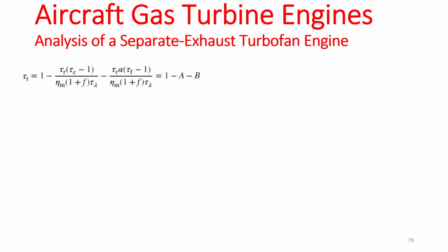That can also mean that the fan temperature ratio can also be so big, right? So what's going to happen when you have that bypass ratio and that huge temperature ratio? You're going to have a negative number. Does that make sense? No, right? Because why? You can't have negative temperatures. We are talking about absolute temperatures. There is no way you can have a negative temperature, right? It doesn't really matter how small or large the negative temperature ratio is, you cannot have it.